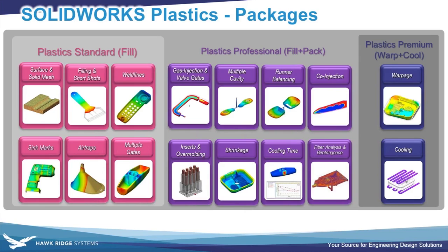Plastics Professional adds some capabilities that any mold designer would want, to help you evaluate a multi-cavity mold, which is something that we're going to need to do here. Things like figuring out what the runner should look like, and then what the full cycle time would be. Not just fill, but pack and cooling as well.